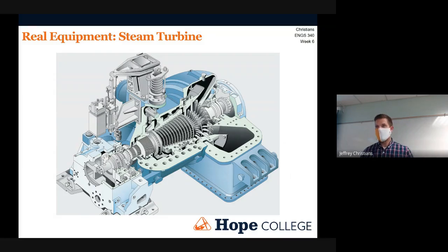So the reason we can't use a Carnot cycle as we have drawn it is because we can't make an efficient turbine that has that happening inside of it. If you have a turbine where a gas is coming in and all of a sudden all kinds of water is condensing out, you have a number of different problems, like liquid water falls out of the system.